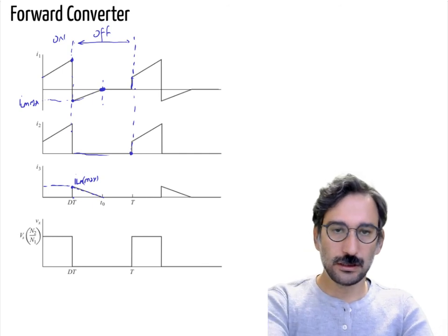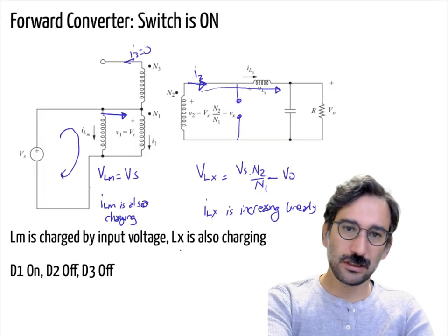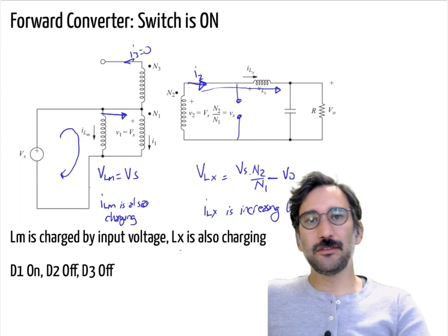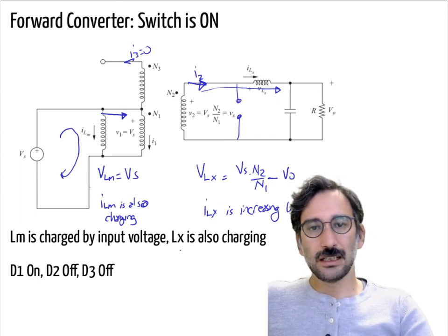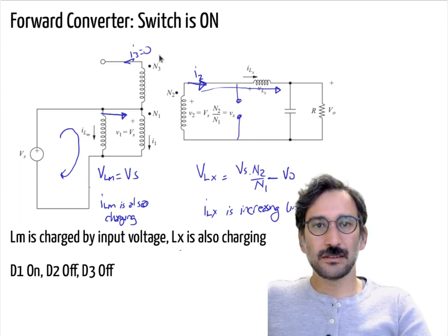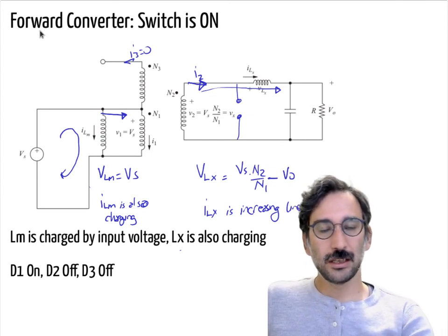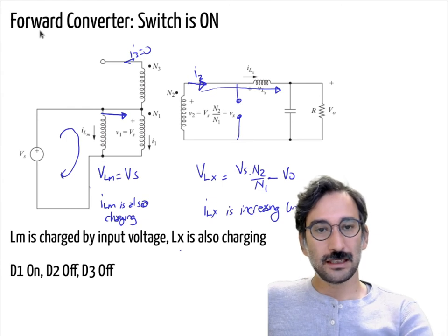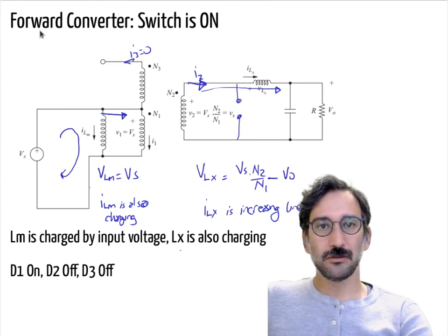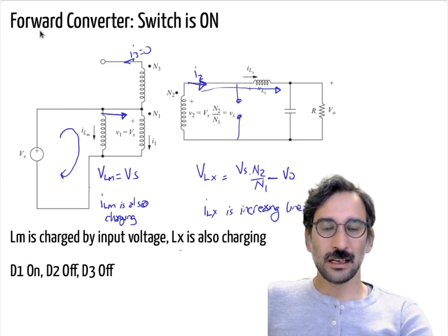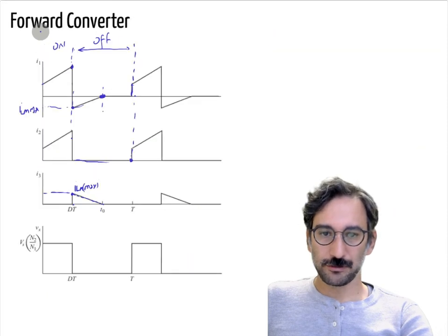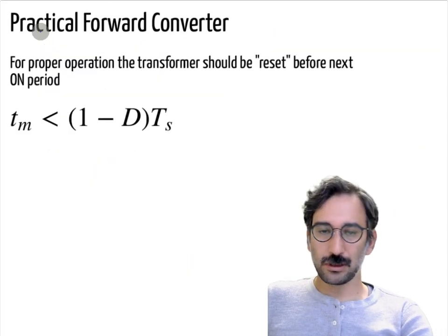It seems quite strange and maybe difficult at first, but the idea of the third winding is just to increase efficiency by sending some power back to the source instead of dissipating it, but the rest of the operation is the same as an ideal forward converter. Anyway, we talked about that one.